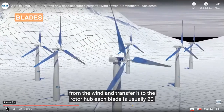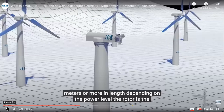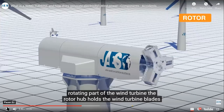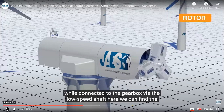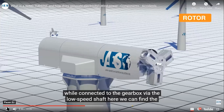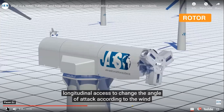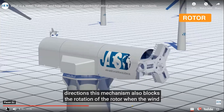Each blade is usually 20 meters or more in length, depending on the power level. The rotor is the rotating part of the wind turbine. The rotor hub holds the wind turbine blades while connected to the gearbox via the low-speed shaft. Here, we can find the pitch control system. Thanks to the pitch control, blades are turned in their longitudinal axis to change the angle of attack according to the wind directions.